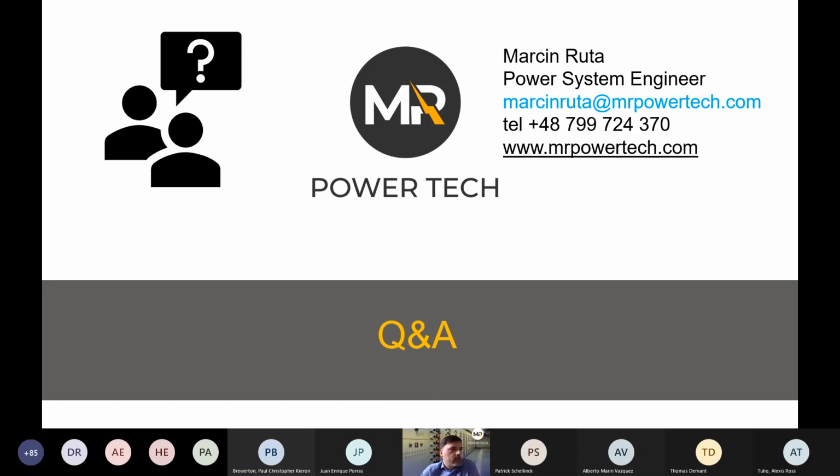Do you need to do an arc flash study for gas insulated switchgear? There are no exposed conductors. That's a good question. Technically, no, because your gas insulated switchgear will most likely also be internal arc classified, as it will be medium voltage. So you can calculate it if you want, but if you don't have exposed conductors where you can initiate the arc, it's hard to say why we would do it. Eventually there will be a cable connection where you can calculate it.